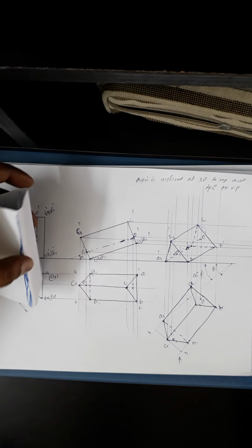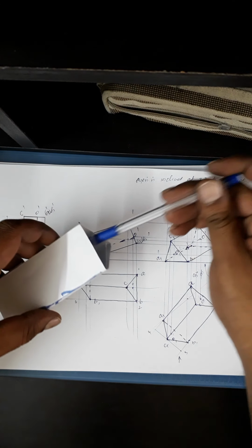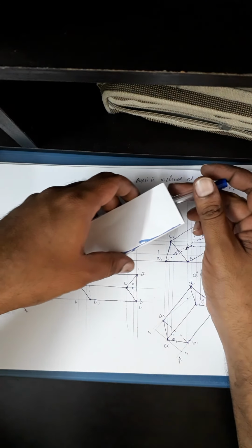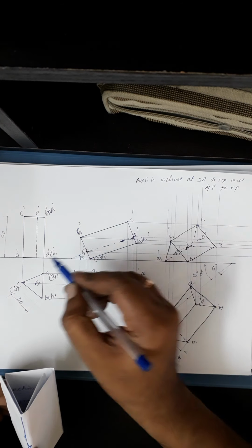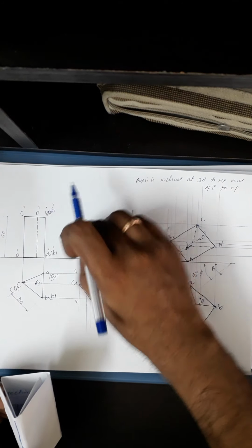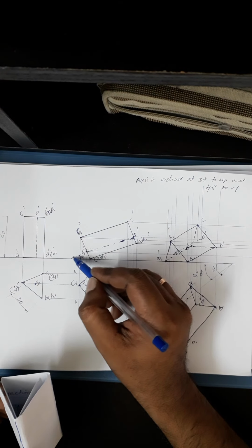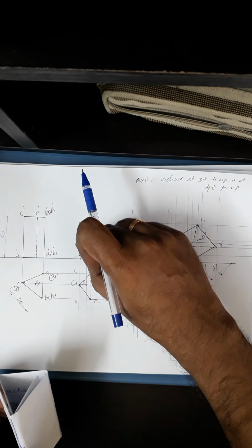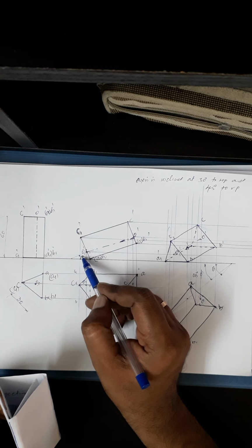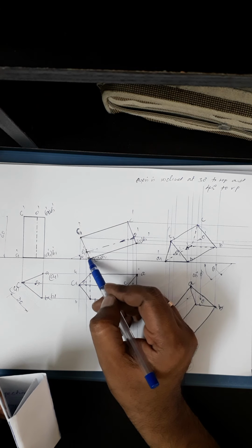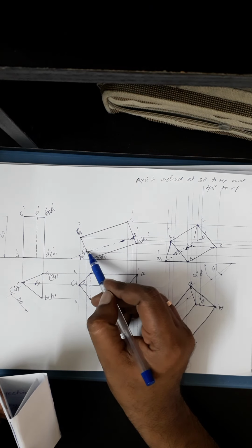Now because it says the axis is inclined at 30 degrees, the axis will be parallel to the surface. So we can go for drawing this base inclined at 60 degrees. I can take this length, mark it here, and redraw this rectangle here. When the base is inclined at 60 degrees and I mark the axis taking this length, draw the axis, and then project, see that the axis automatically makes 30 degrees. If this is 60 degrees, this will be 30, and this will be a right angle triangle, because the base and the axis are mutually perpendicular.